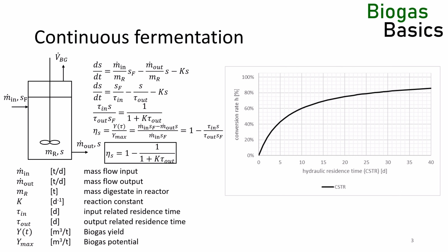But back to the growth of microorganisms. We notice that this cultivation has no washout point. We can lower the residence time, and while the conversion drops when the residence time goes down, it only reaches 0 when the residence time is 0. Remember, with the monokinetic we saw a washout point and a turbidostat region, so the first order model has limitations, especially at low residence times.